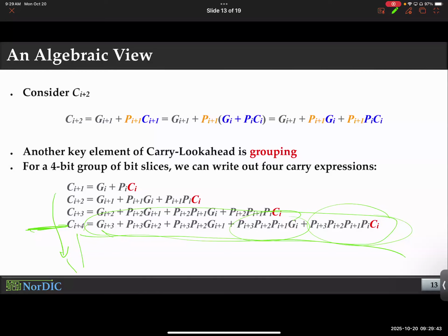So just imagine how the circuit will look and how much capacitance you'll be dealing with. Yes, you have all the inputs available right away. You don't have to propagate. But then just to calculate the carry, it will take you more time than what it would have taken to just propagate the carry. Does that make sense? And nobody just makes up these numbers. They do simulation, by the way.